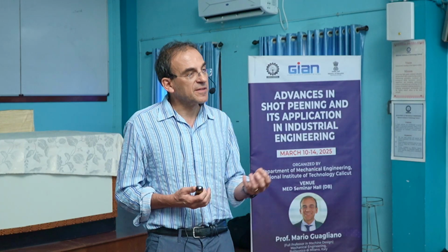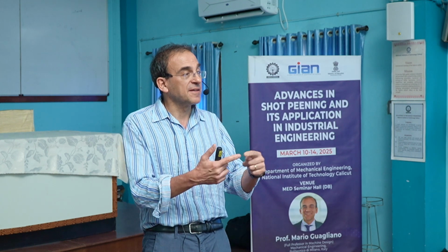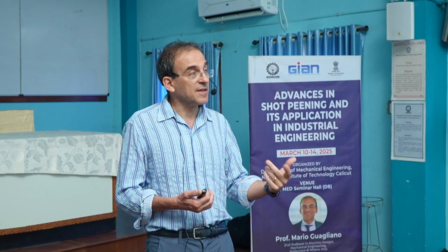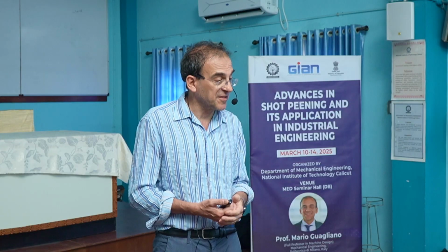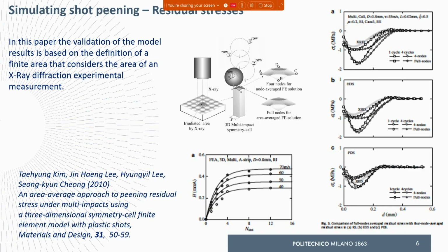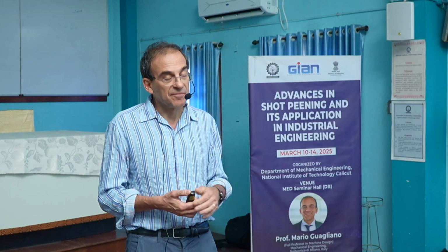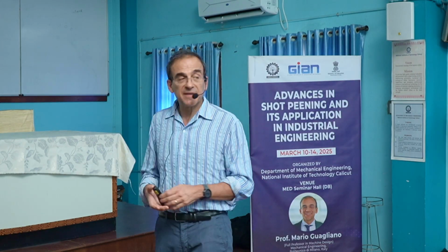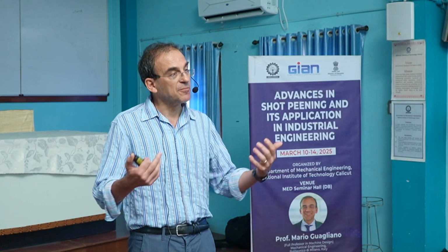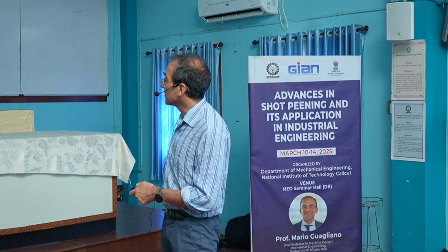The XRD diffractometer is measuring the residual stresses not in one single spatial point, but in an area around the point. That is to say, the X-ray spot has a finite area that is circular generally, and they have developed the model in such a way as to correctly represent this area, and also the analysis of the results has been done by considering not a single point, not a single finite element, but the complete area to have more consistent results. And the results they obtained were all satisfactory.